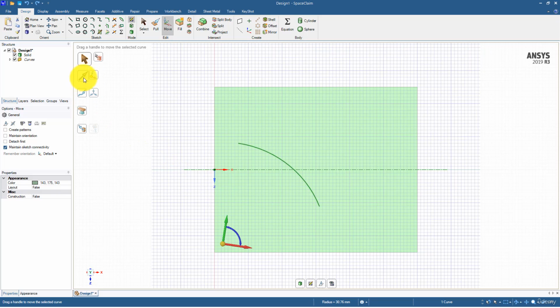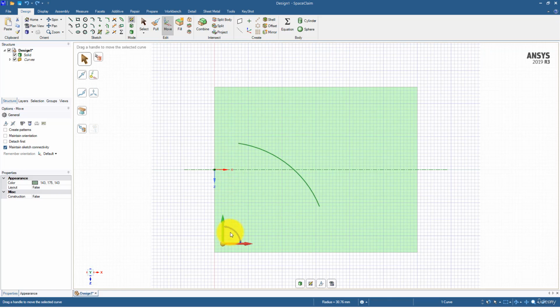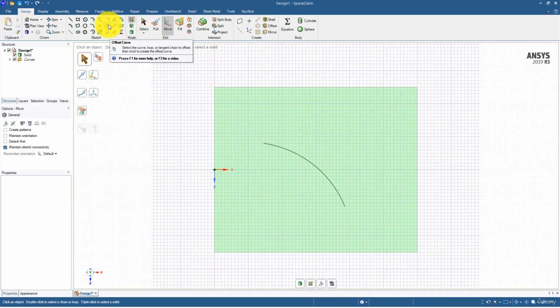And if you want, you can also move this model slightly towards the right side. So choose this line, and the direction I'm going to decide is this line. So there's some angular twist in the inclination, but after making this as a reference, now we have the straight lines for these two axes. So now I can move slightly to the right side. Again, this is very arbitrary. I just want to keep this curve in the middle of this cylindrical body.